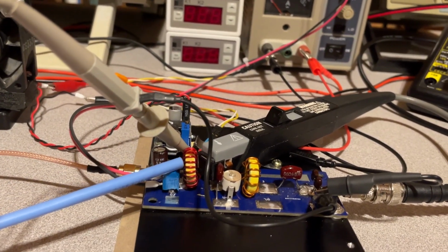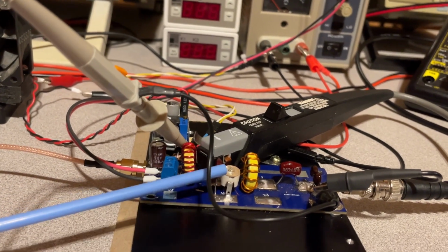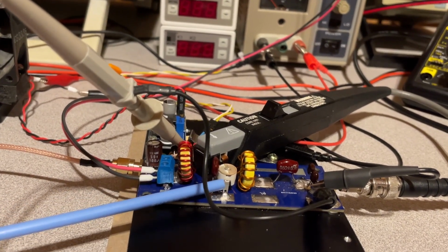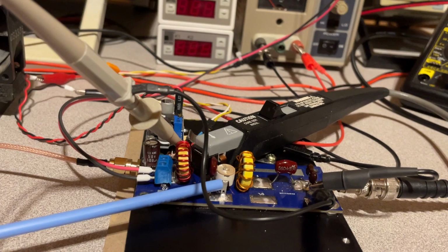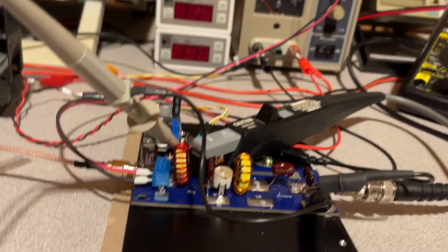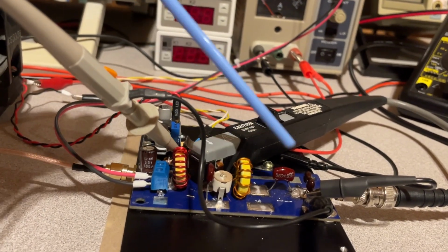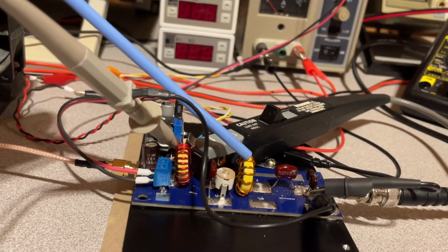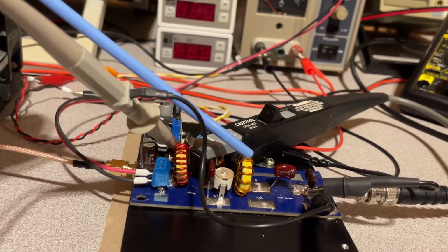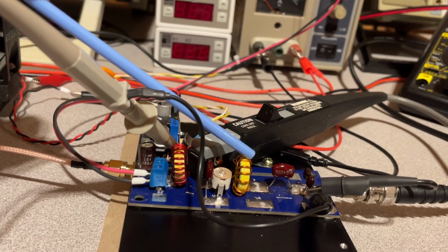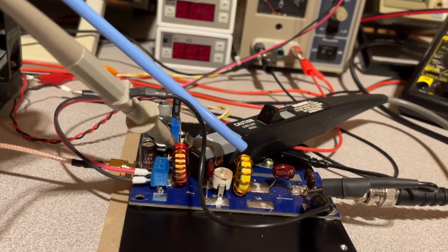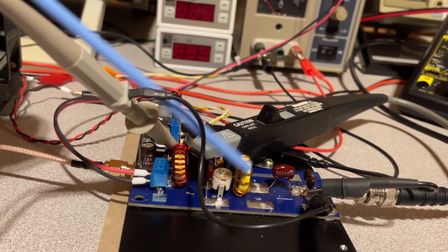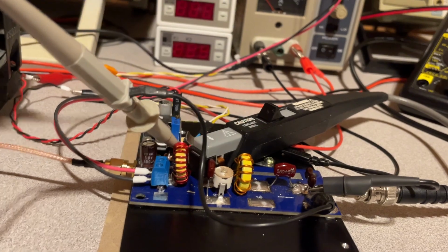And before I go, this is a look at the Class B amplifier. Here is the RF choke. This is the shunt capacitor. I also put a variable capacitor in there so that I could optimize the value. This is the resonator here, and then the matching circuit. And again, we had two inductors in series, so I just combined them into a single inductor, and this would be considered a high Q inductor with the powdered iron core.